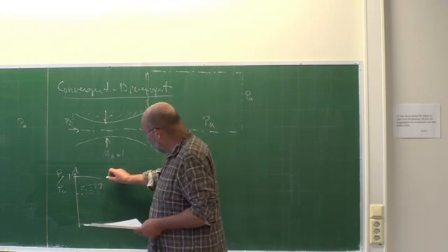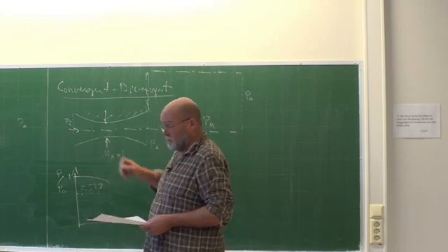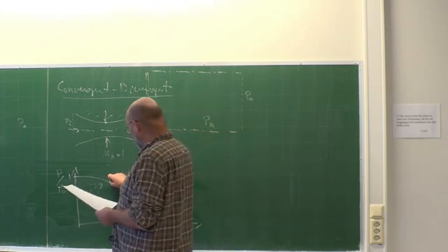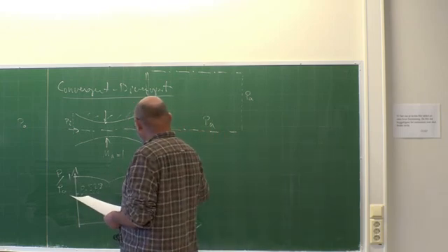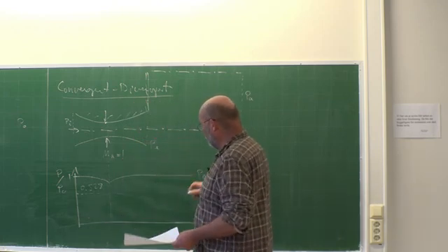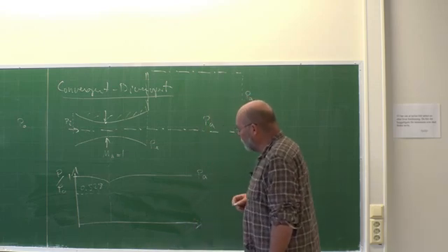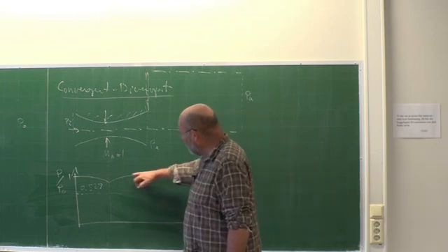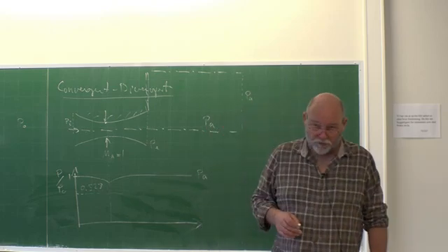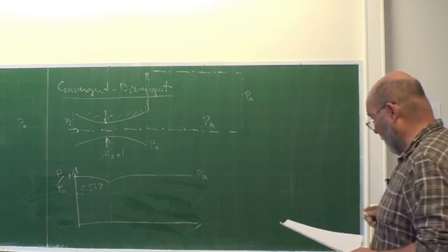And then, if the driving force is not strong enough, you have the lowest pressure in the narrowest opening, and then the pressure is just going to go up again, and then all the way over here is going to find the P atmosphere, or P reference, or whatever you call it. So the tiny little pressure difference here, that's the driving force. Not strong enough to create a shock. So that one is good enough.